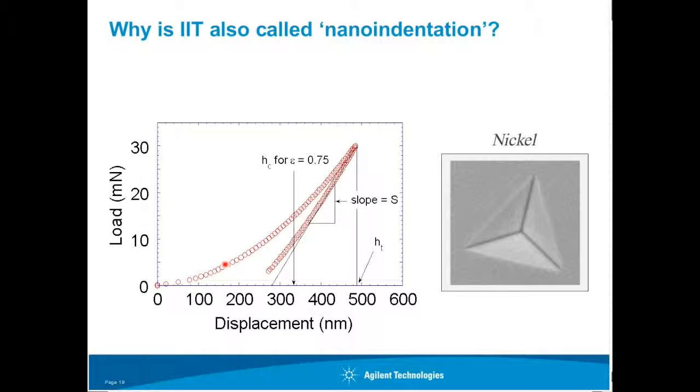If you have an indenter that's sharper, like a cube corner indenter, on metals, you will generally measure a higher hardness on the material than if you had used a Berkovich indenter, okay? And that is because the cube corner indenter is causing a higher strain in the material, and so you measure a hardness that's proportional to a higher yield stress. Now, in some materials, that doesn't matter. Materials that don't have any mechanism for work hardening, that doesn't matter. So that's really what you have to pay attention to.